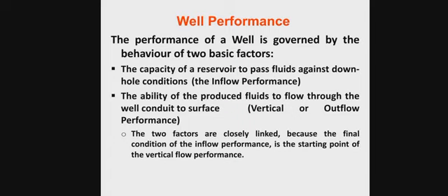The two factors are closely linked because the final condition of the inflow performance is the starting point of the vertical flow performance. When the fluid leaves the reservoir, it flows through the wellbore, through the production conduit, and once it reaches there, that is the end of the inflow. From there starts the outflow. So the two factors are closely linked. Now let's talk about the well inflow performance.